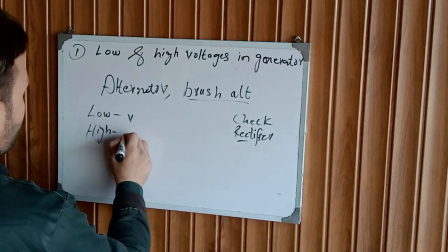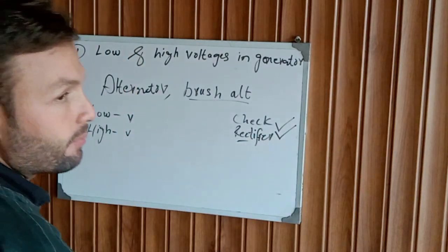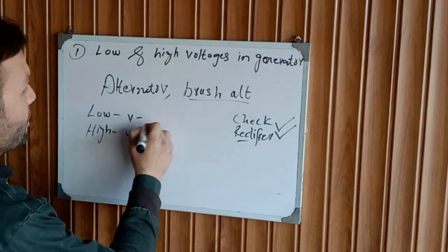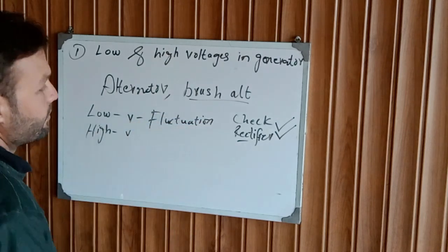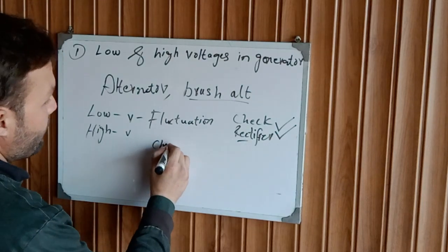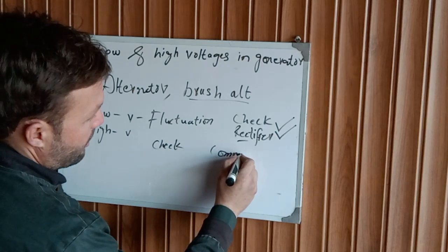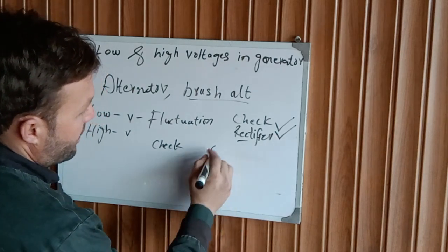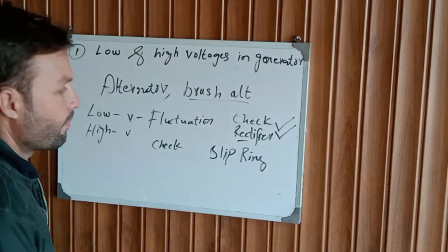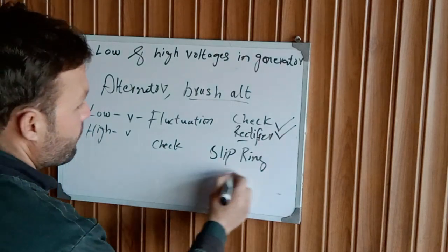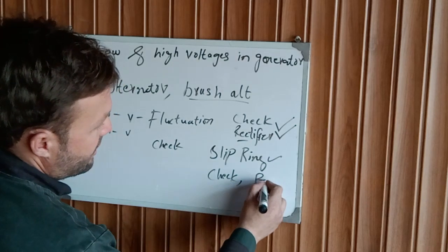High voltage: check the rectifier assembly. Fluctuation: check the slip ring, and check the brushes.